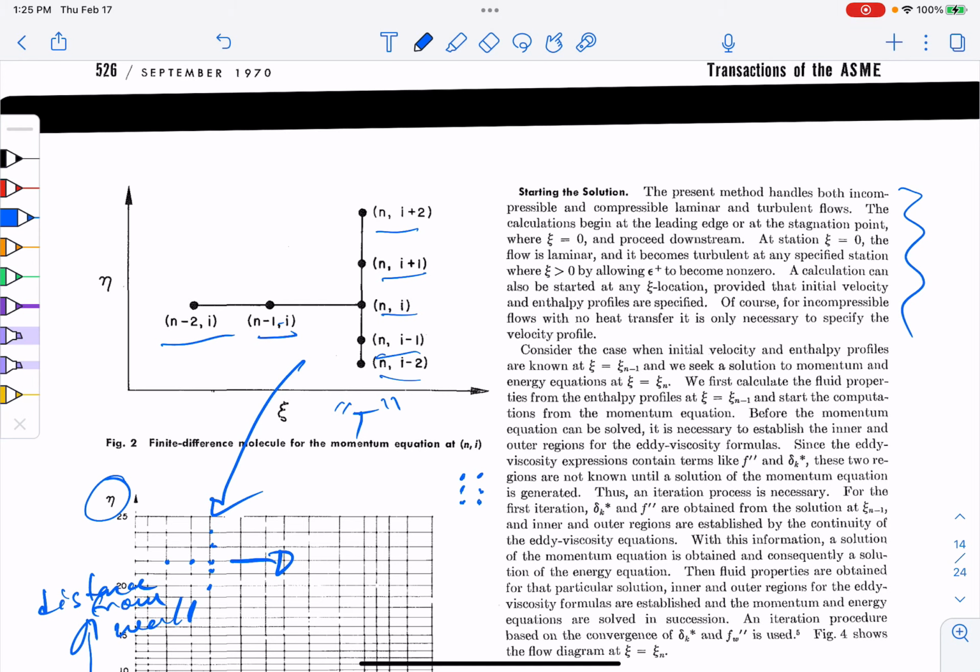And then you would say, well, how do I let the flow transition from a laminar flow to a turbulent flow with the same code? Because his code is not really a laminar flow solver. Now, if I set the eddy viscosities, inner and outer, to 0 in my code, the whole code reduces to a laminar flow solver. So using that little trick, how could he do a flow over a nose cone of an F-18, which is pretty close to axisymmetric, and simulate transition?